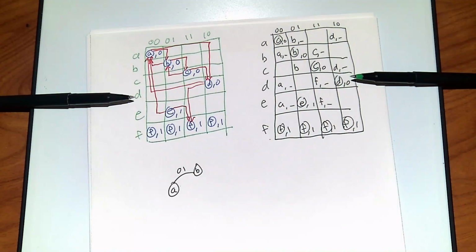Now realize there might be some user cases where they don't have a condition that has to happen there. You could have some cases that could be a legitimate transition, a one-bit flip on an input, and it just doesn't matter to what their requirements are. Then I leave it blank again, because now I get to pick whatever makes my life easy. I can decide to make it stable, I can make a transition somewhere else, whatever.